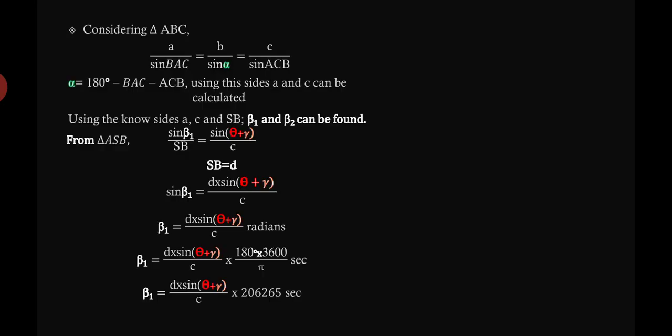Now if you take a triangle here, I'll show you. This is the figure. In this figure, this is the observation made from one station and the angle is there, and this is the observation made from one more station. The darker one is the observation made from the original station, and the dotted one is the observation made from the satellite station. Now what are the things you are going to have? You are going to have three different sides and three different angles. If you know one side and the remaining angles, you can easily determine the angle, and if not, you can get this beta angle too by using this formula. You have to keep in mind, only the formula is required to solve this problem. They have not asked any problem here.